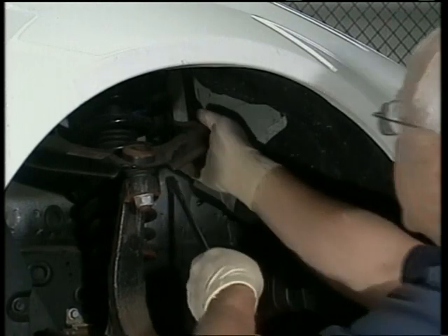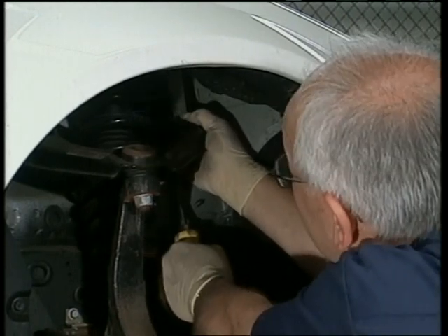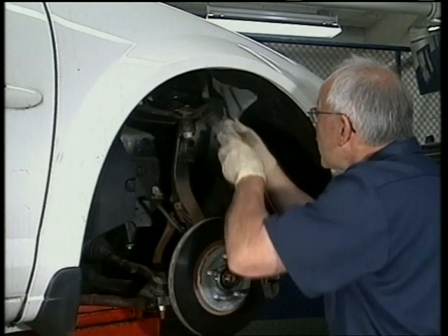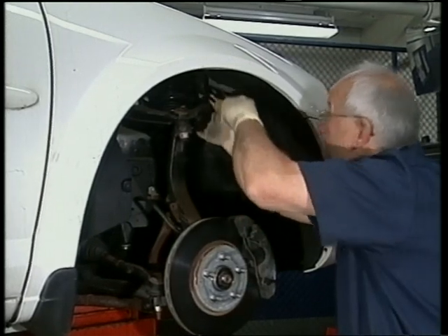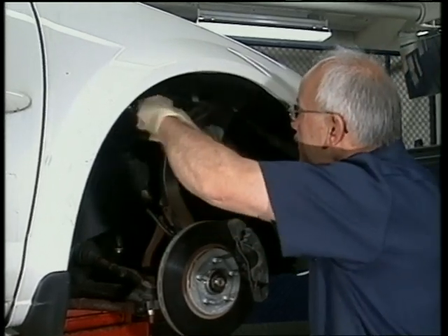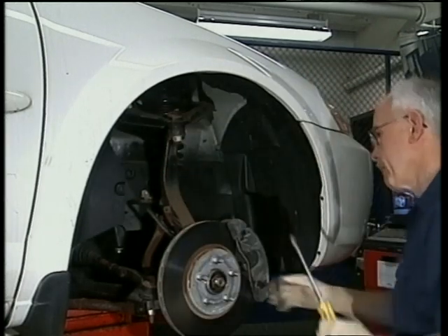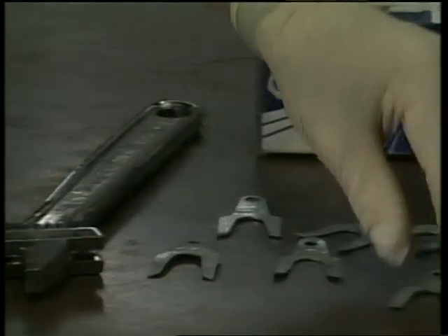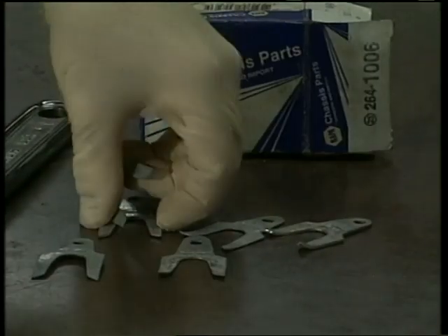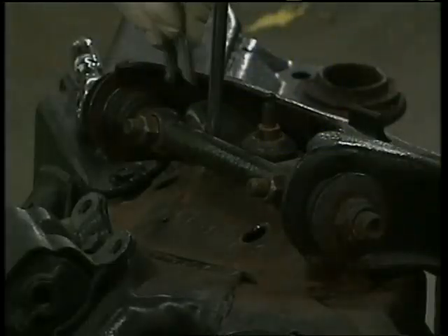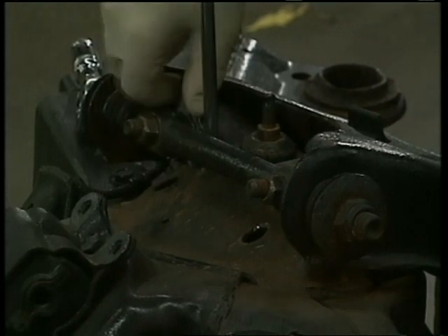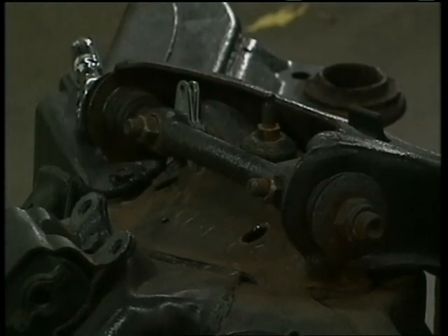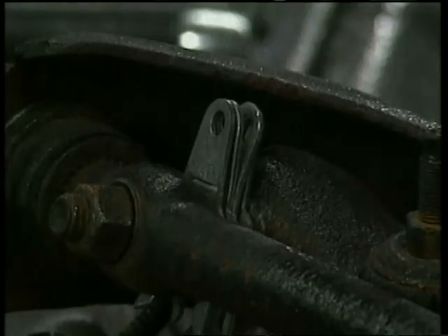Caster is not adjustable in most front-wheel drive vehicles, but is built into the frame, so it's important that your frame alignment be true to the manufacturer's specifications. Some suspensions are adjustable and have slotted holes for adjusting caster. If the suspension is not adjustable, kits from manufacturers can be used or shims can be placed on the upper or lower control arm systems. Inserting shims of different thicknesses in the front and the rear of the control arm changes the caster.